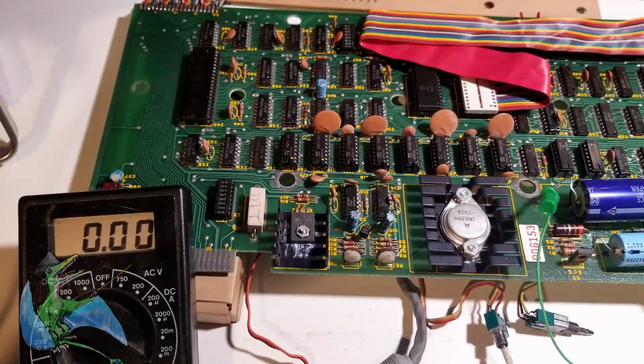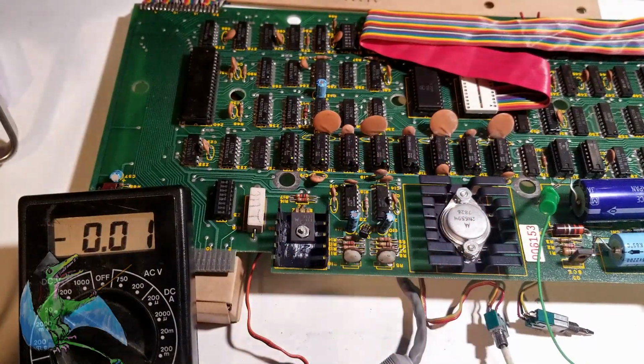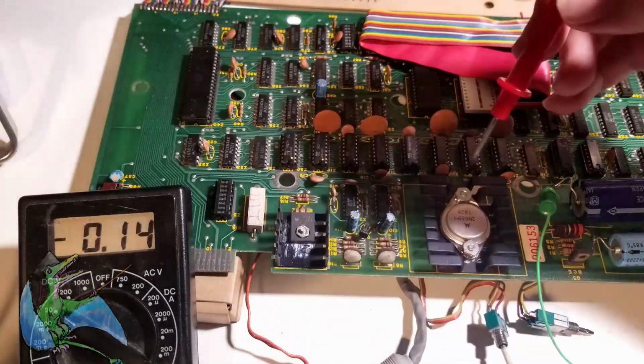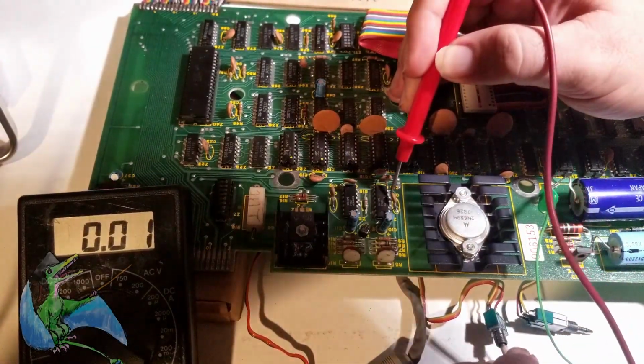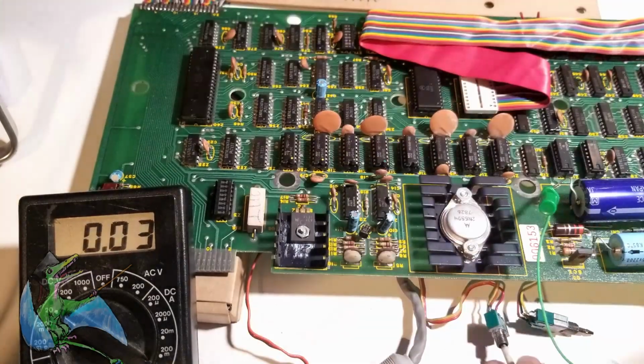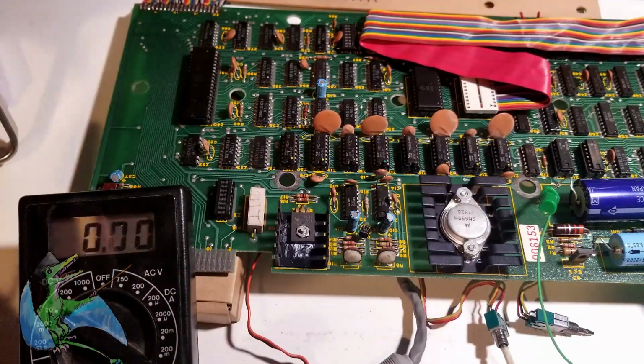Now, on pin 5 should be the voltage that we've set with the divider resistors. That should be the voltage we're aiming to regulate at. So on pin 5, we should see 5 volts, which we do. So that's looking good from the voltmeter's point of view.